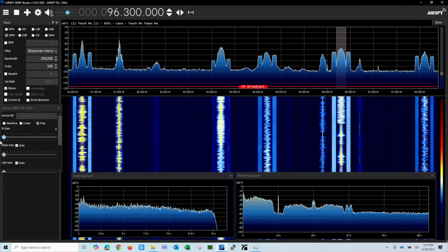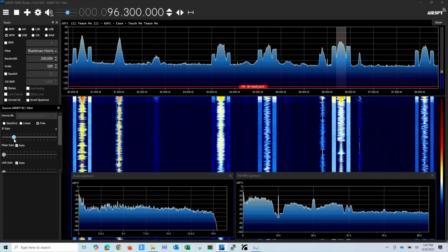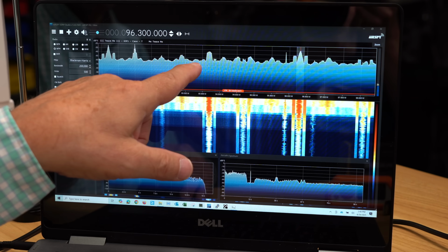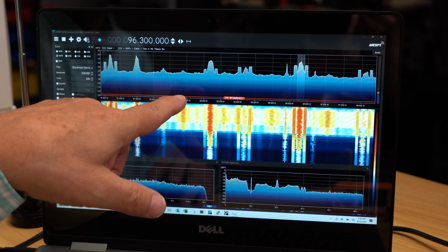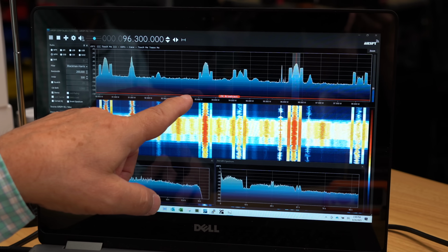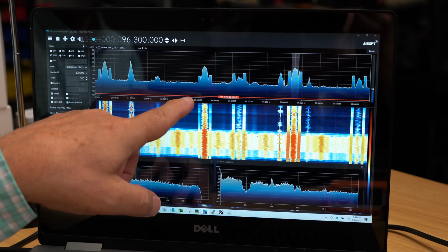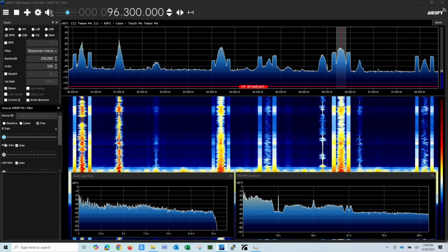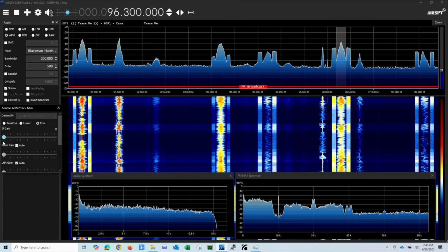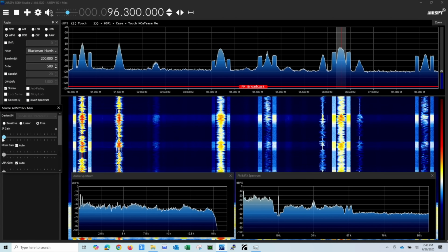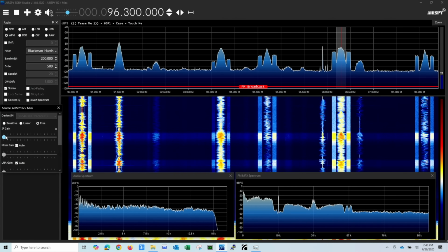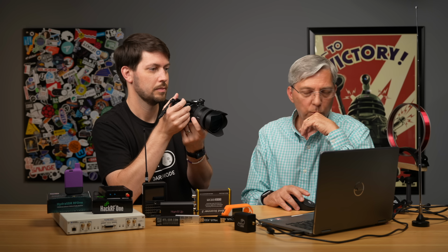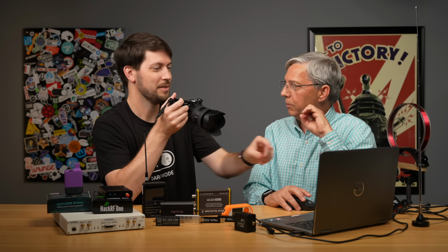But just to show you, if you start pushing the gain, I'm getting a higher level of noise, and eventually I'm amplifying so much noise, the signals aren't as clear. But there's a point where you can trim it down, where you're getting some gain, but you're not messing with it. Mostly all I'm doing right here is raising the noise floor and the signals. There are times when the signals will go up, but the noise floor won't go up as much, and that's a good use of gain. But there are so many settings on these. It's wonderful to play, but it's a pit, so you don't do it when you're ready to go to bed.